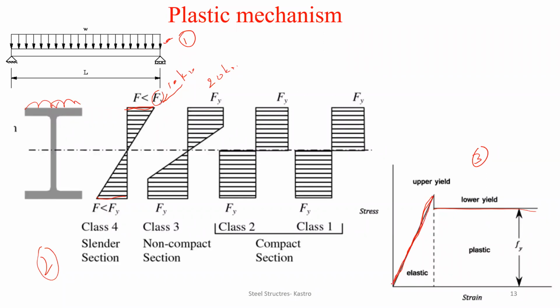One is the linear line, which is in the inclined way, and the second one is the linear line, which is in the horizontal direction. Now, once you analyze the member, or once you simplify the section, what happens here is, if you keep on increasing the load, according to the theory of plastic analysis, the highly stressed fibers, once they yield, don't have any additional capacity to resist the loads. Understand this concept very carefully.